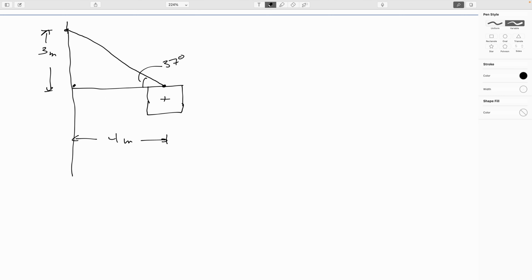And then right here, we're going to have a hinge. And so the hinge will be exerting a normal force. Now, what I'm going to want to get out of this is how much is the tension in the cable, and what is the magnitude and direction of this normal force. So at first you might look at it and say, well, gee, it's got to be perpendicular to the wall, duh. And it actually turns out that's correct in this case, but let's say we didn't know that.